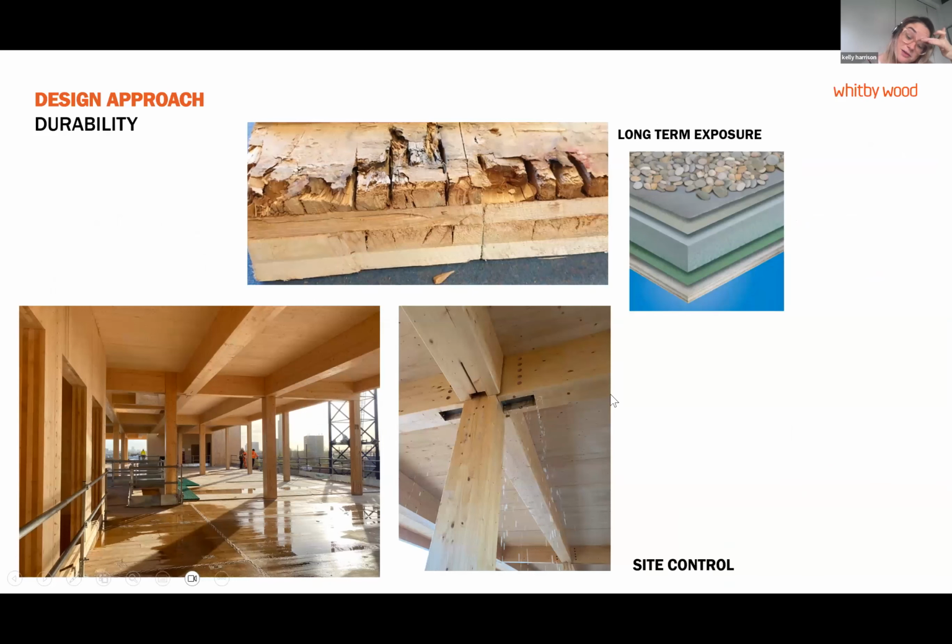So let's talk a little bit about durability, because it's an issue. Timber gets wet and it rots. It's a fact. We know it. We've seen it. CLT in particular is a super material. So actually, this is an image from a report a couple of years ago. When it gets wet on the top and rots, you can't even see it at the bottom because it's so good that it doesn't soak through, and you can't see it like you would with plywood or a joisted roof. And so we have to stop this happening.